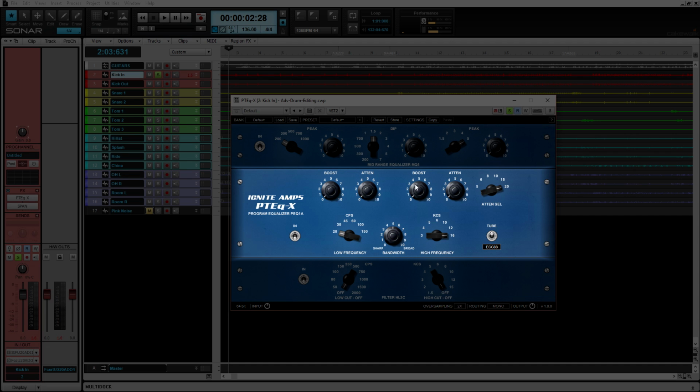After that, you get the high frequency boost. So again, controlling the amount of gain applied to high frequencies. Nothing crazy. And again, when set to 0, no boost will be applied. High frequency boost selector, okay? 7 positions here. High frequency attenuation. Same as all previously mentioned. And again, set to 0, no audible cut.